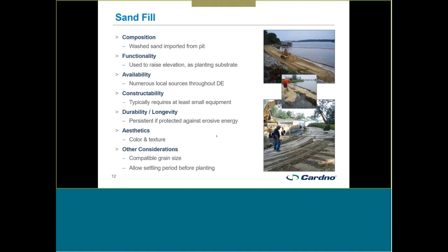One of the things that's nice about it is it's not really prone to soil compaction in the same way as some of the other more organic substrates are. So just backing over it with a bulldozer a couple times beds it down pretty well, but it's always recommended to let at least a couple tide cycles go through so that it seeks its own level, because that elevation, as we'll see, is pretty important.